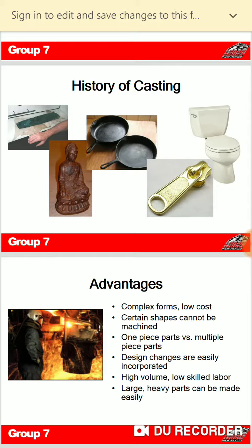Now the second type is plaster, concrete, or plastic resin. Plaster and other chemical curing materials such as concrete and plastic resin may be cast using single-use waste molds, as noted above, multi-use piece molds, or molds made of small rigid pieces or of flexible material such as latex rubber. When casting plaster or concrete, the material surface is flat and lacks transparency. Often topical treatments are applied to the surface.